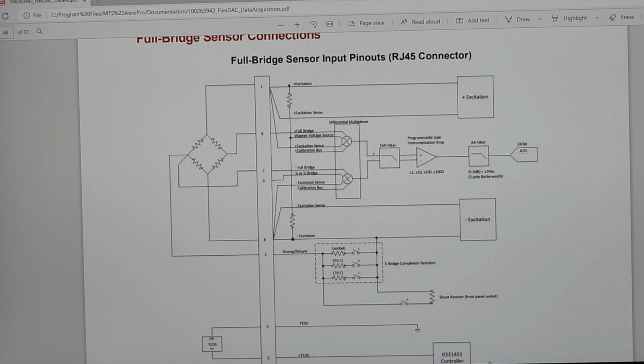And part of me says that the LVDT piece, so when we created a new sensor, the LVDT was in the list of sensors for drop downs. My gut feel is that that's there as a remnant of what's shared between FlexTest hardware and FlexDAC hardware, because the list isn't necessarily pared down just to what's capable here. So typically, if you have that and you're hooked in, then it would be able to see the conditioning off of the FlexDAC or FlexTest, and then pull in LVDT.